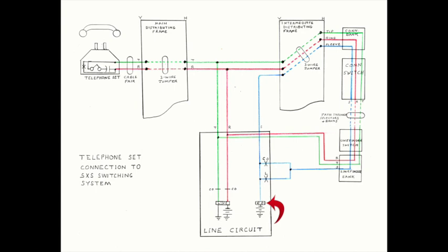In the line circuit, the CO relay winding is energized over the same sleeve lead path as the F relay's primary winding. The CO relay operates and locks over its own make contacts. Break contacts of the CO relay release the line relay.